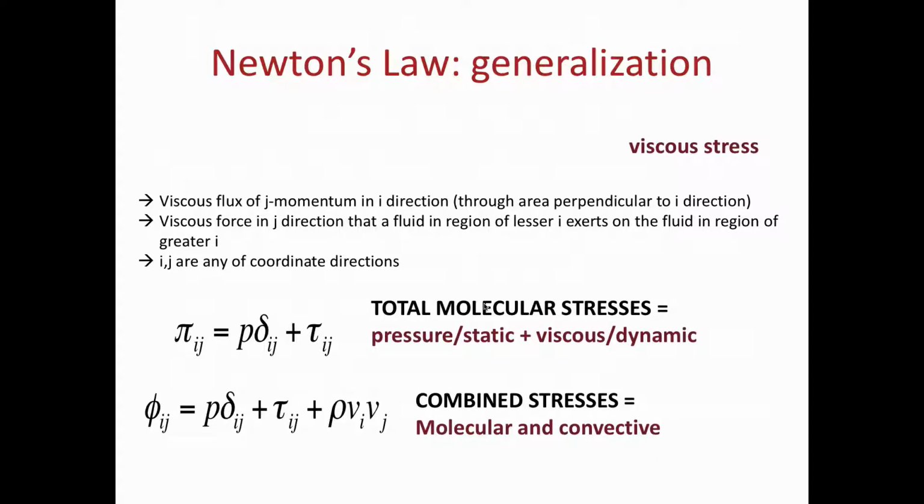And then we also realized, I could actually have things just simply flow in with a different fluid unit, if you will, into my geometry because I'm kind of standing still in a coordinate system. So stuff that flows in is rho v, and it flows in with another velocity, v. So rho vv is our convective stress tensor, and its coordinate description is rho vi vj when I look at the individual element of that tensor.